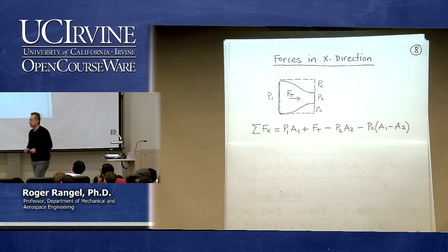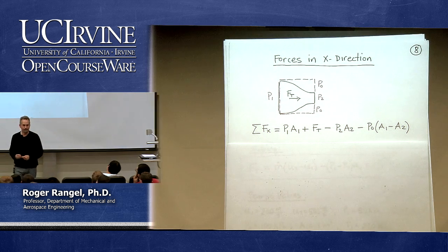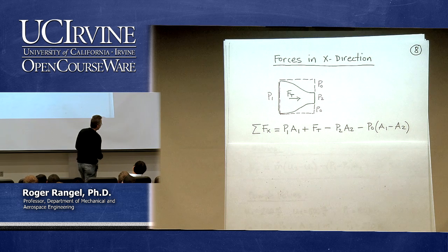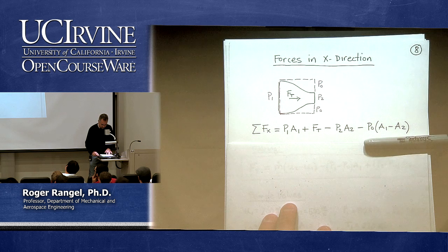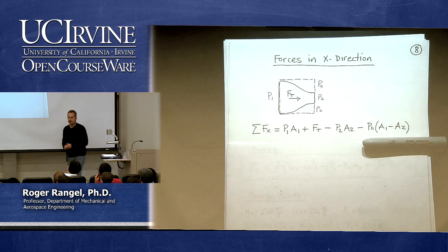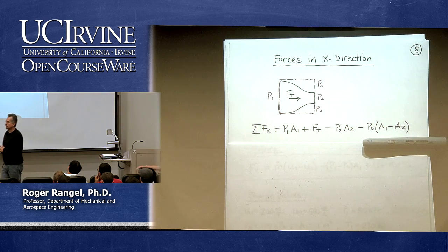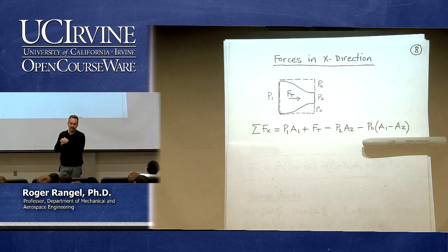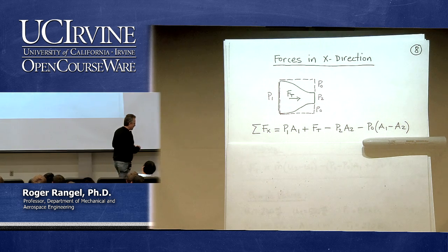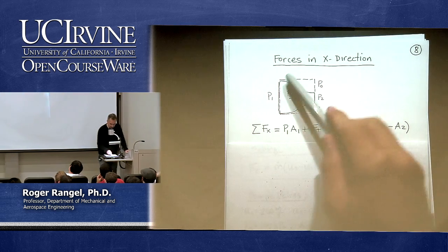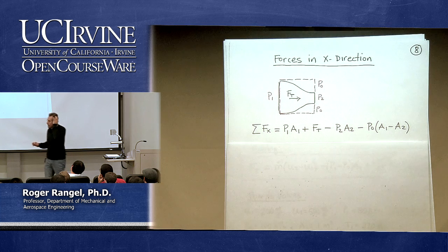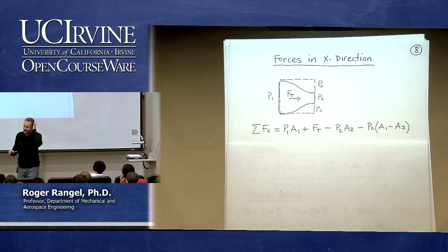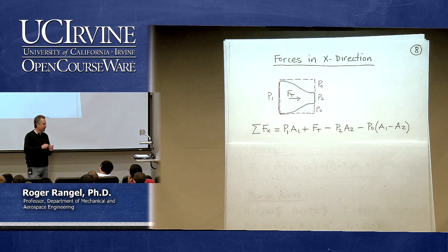How can you justify that term? Where did this come from? That's a good way to look at it. That's probably the best way to look at it. You have to step back and think of statics, right? On the curved portion of the engine, if I'm looking at the horizontal force, how do I find that horizontal force? So this is straight back to chapter 2. You know how to find the horizontal force on a curved surface.